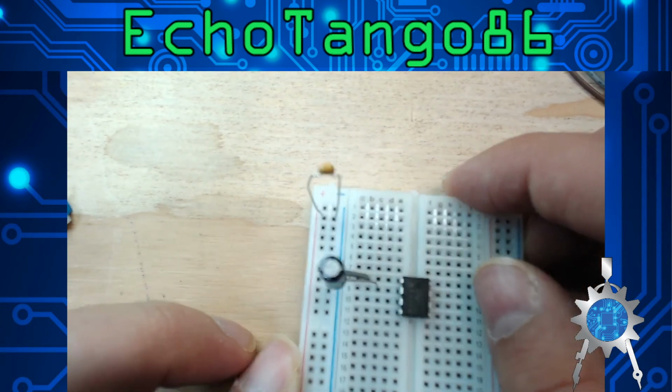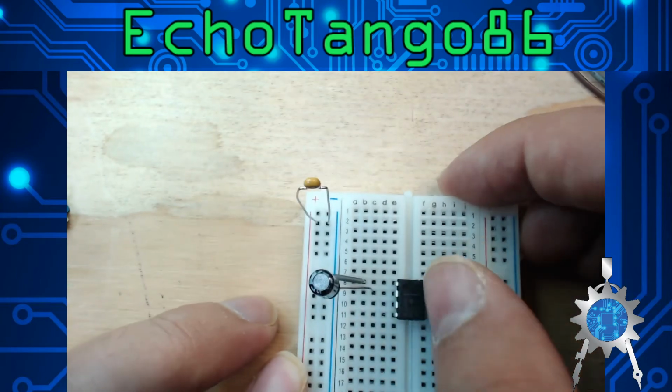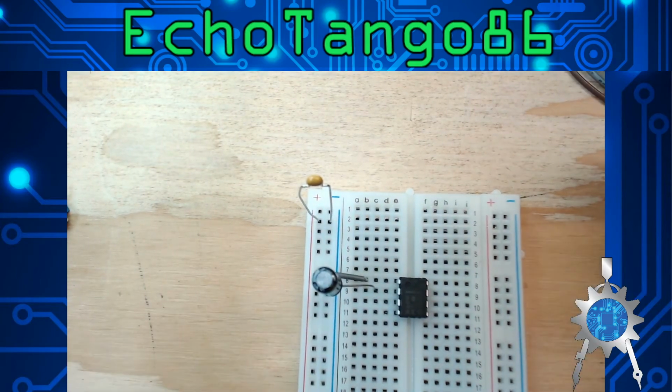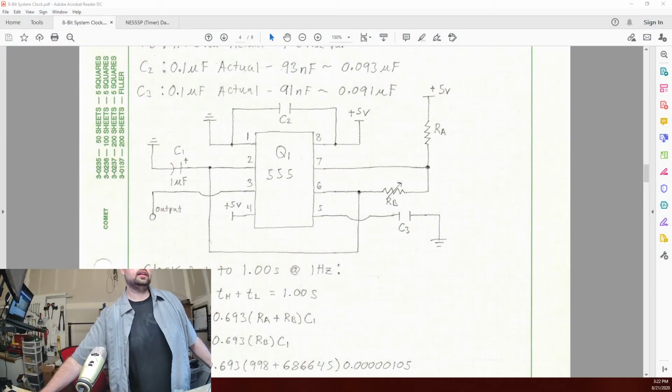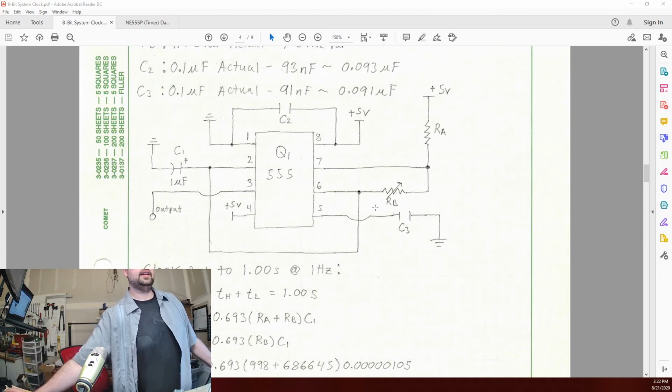Put in the negative on the negative sign, and then goes into pin 2. Excellent. Now, we need to connect pin 2 with pin 6. We want to connect it from here, bring it over, and connect it to pin 6 in front of the potentiometer.